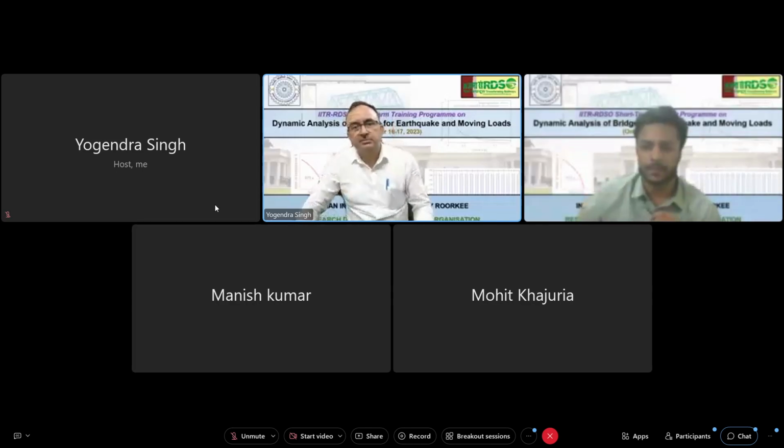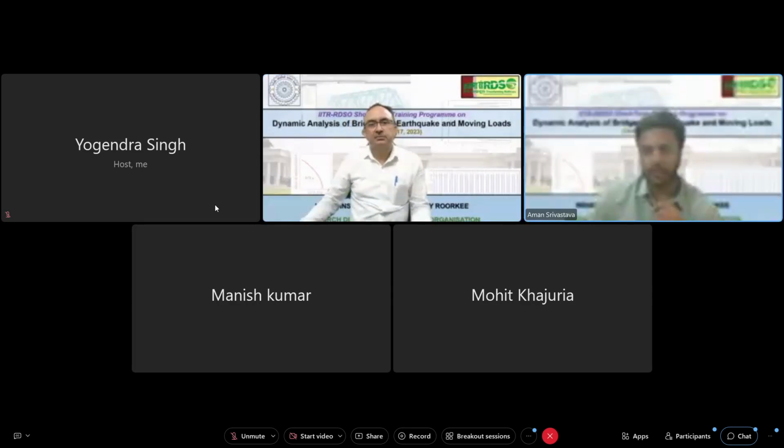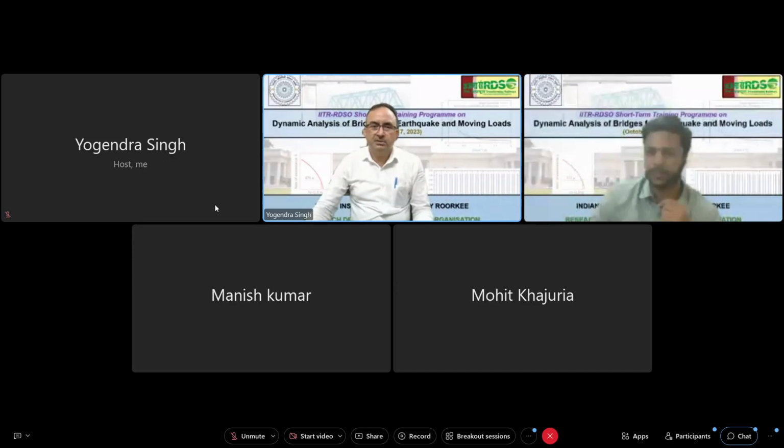Sir, we'll take the last two questions now. Okay. Mr. J is asking, we are required to ensure no collapse under MCE. However, under ULS, we are checking for DBE. How are we ensuring no collapse under MCE as per Indian standard? Actually, we are not doing that. Under any code, we are not doing that. The current framework of all our codes, which is force-based design, it can't be done. If we want to ensure no collapse, we have to go for performance-based design.